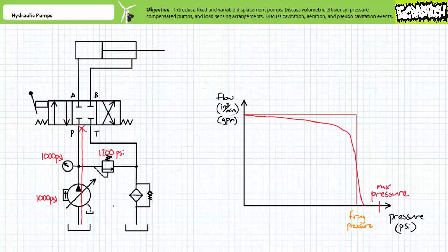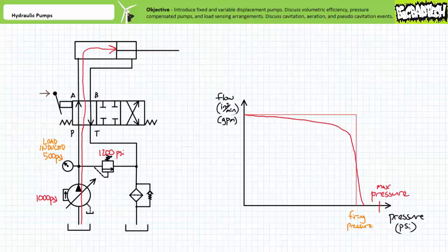Given pressure is below the setting of the main pressure relief valve, it remains closed. Pressurized oil is just sitting there, ready to be put to use. This is what is often referred to as a high-pressure standby mode. High pressure, no flow.